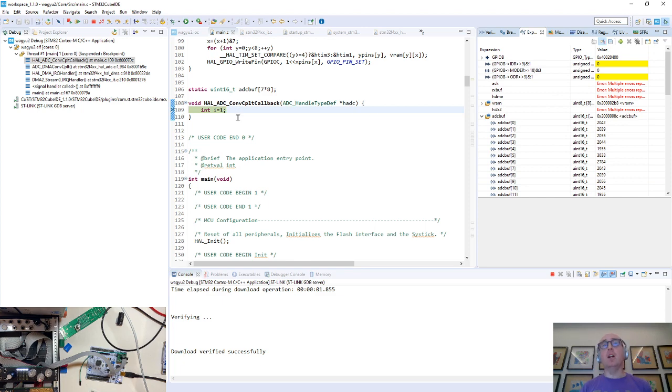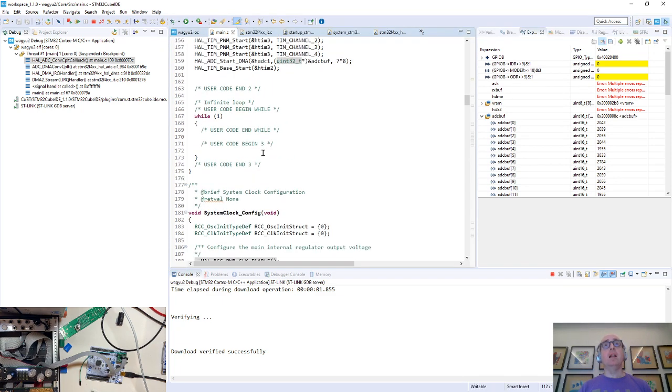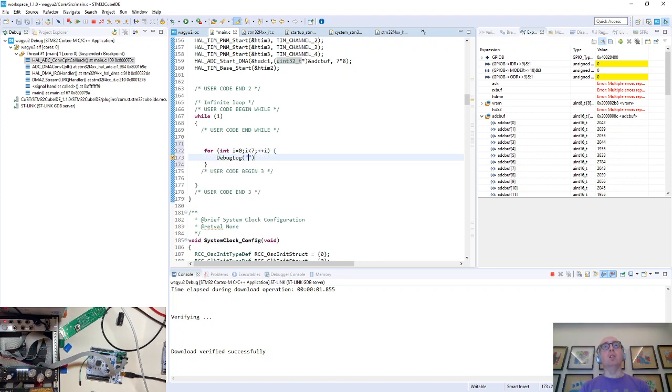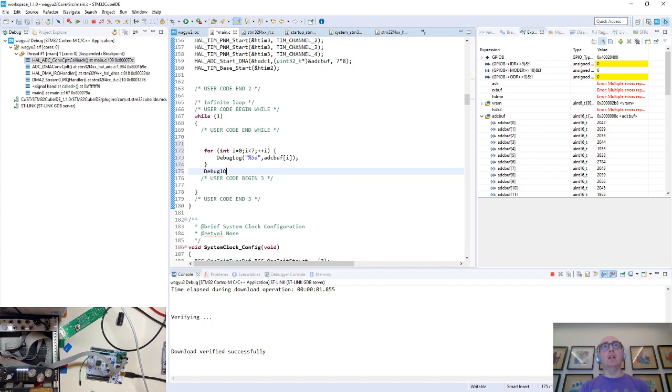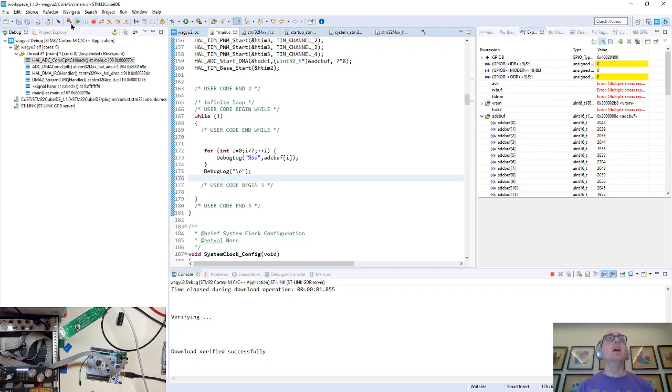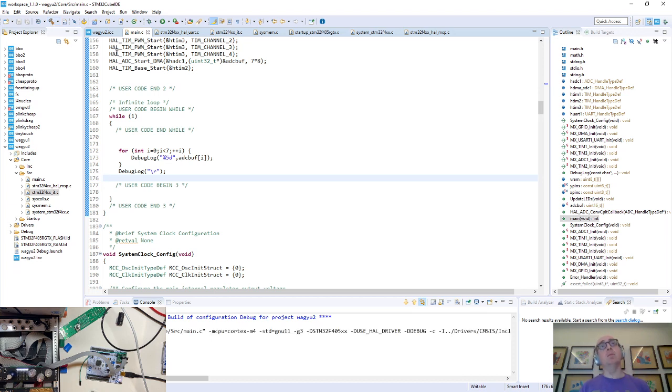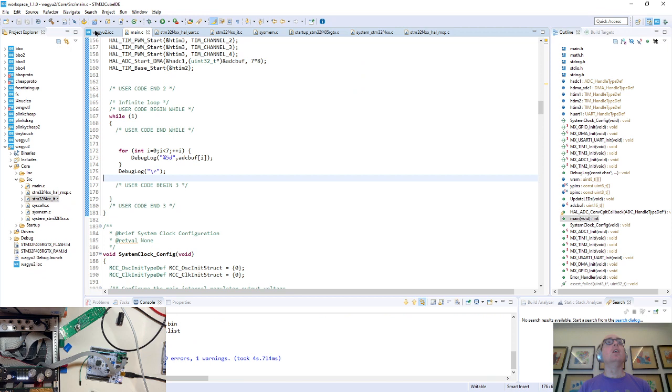So it's working, people. To prove it, let's use our UART. We haven't used our UART for very much, so let's go for int i is 0 to 7, debug log percent, that'll do, ADC buff i, we'll just take the first one, sorry, the 7 channels, and then at the end we'll rewind the line, and we will stop, and we will compile. And then we will twiddle knobs and look in PuTTY and see whether or not it's updating. That's what the chat says.